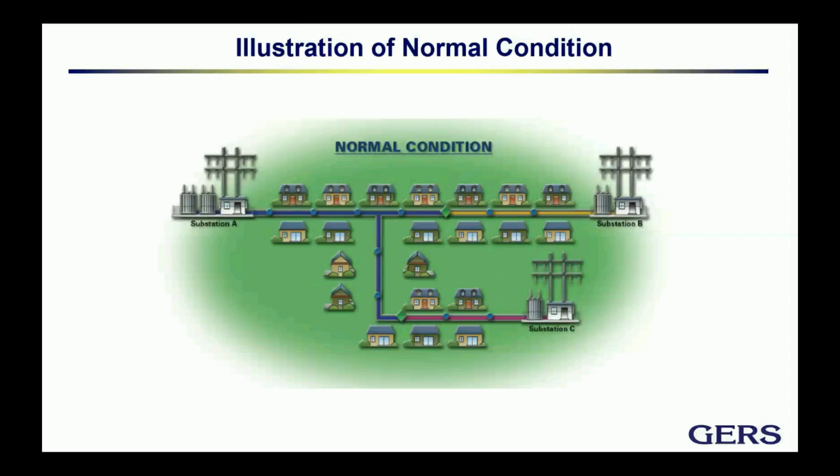Now, when we have the service restoration, mind that normally utilities can first have what is called the upstream restoration. That is the restoration to all those users that were first fed from the feeder. Now, those users that are in other sections of the faulty feeder, but sections which are healthy, could be transferred to healthy feeders of the vicinity.